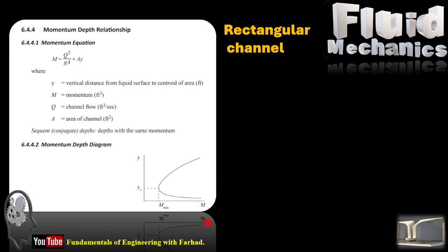This is M, the momentum equation, and y is depth, and yc is the critical depth, where the Froude number is equal to 1, and this is the minimum specific force or momentum of the fluid. In this equation, y stands for the vertical distance from the liquid surface to the centroid of the area in terms of feet of water, Q is discharge, A is area, and M is momentum or specific force, another term for that.